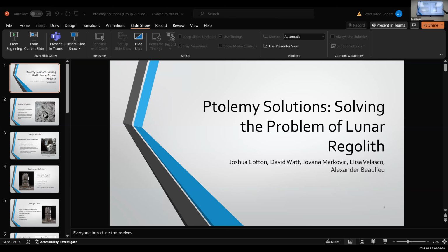So here again, we have an image of the individual quadrants. As you can see, the hooks that the tarp attaches to at the top. We originally chose the exact same material that we used for the outside of the capsule, but we changed that to aluminum 1060O because we want to have a factor of safety of 1.5. We have a width for each of the capsules, because there's 2. We chose a width of 0.44 meters in diameter.